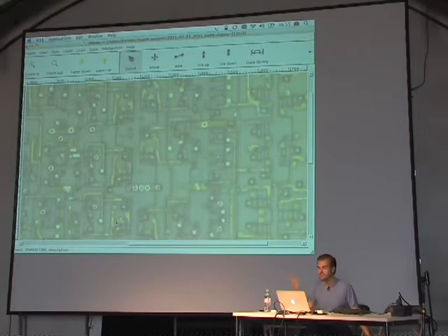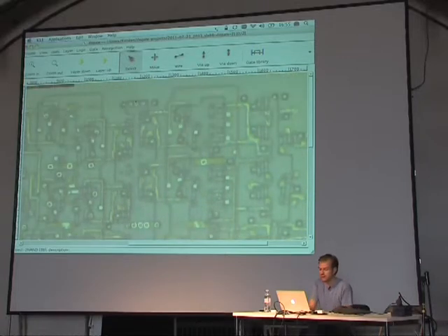You need to look at each gate one by one, finding out the actual function. Again, this is highly obfuscated, and even these are not so hard to figure out. All the other chips we looked at are actually trivial to figure out. If this seems like magic to you, go to siliconzoo.org. There are lots of examples of how little functional units work, described with what they actually do. So that's the first step.